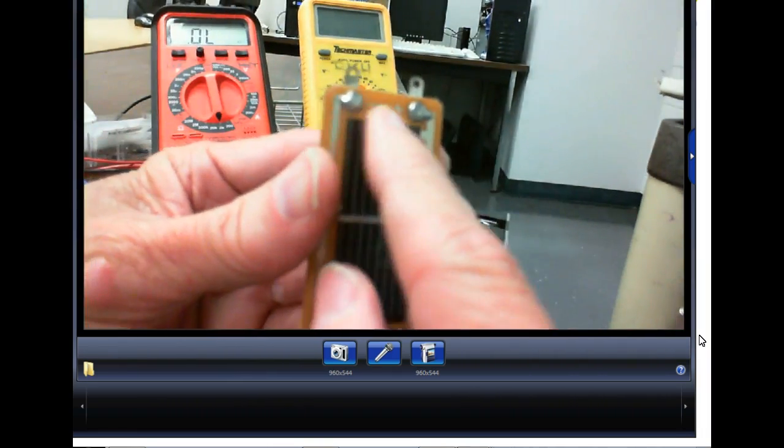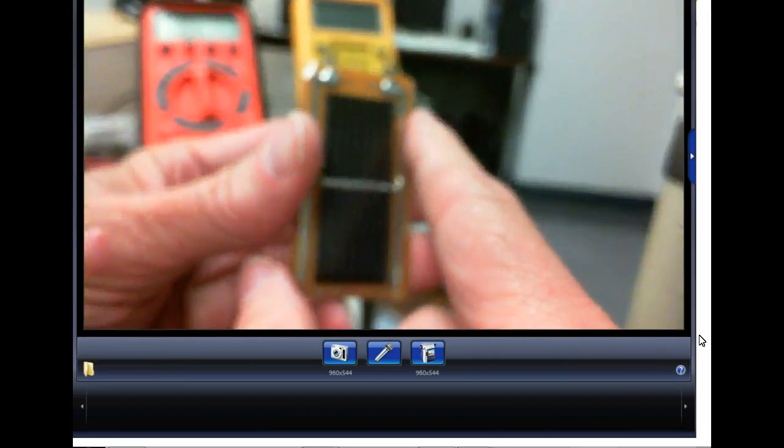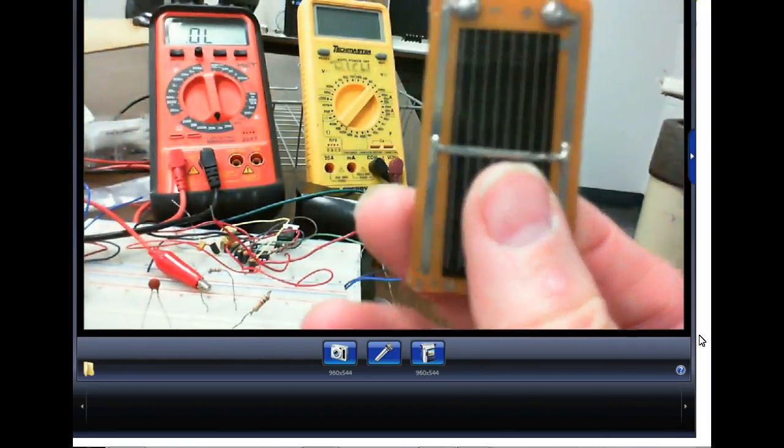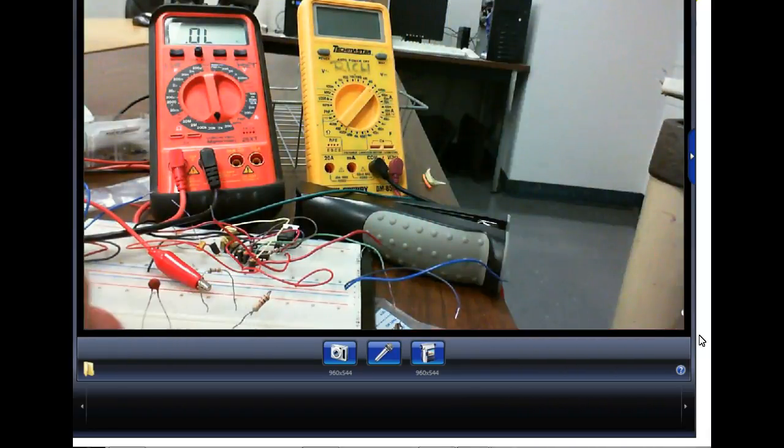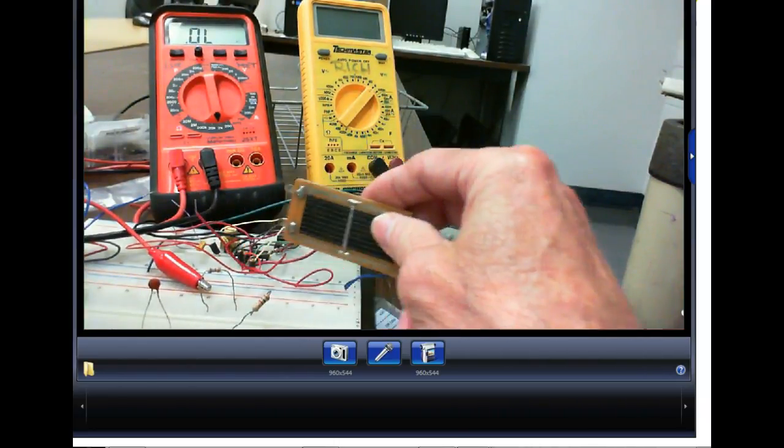She says that diode on the solar panel don't work anymore. But it's got a plus and a minus, and this guy's got two terminals up here, so we can hook in series, or we can hook in parallel. These guys do not vary their resistance. So my thermistor, what would I have to do on that thing? Well, I'm going to have to put it in series with a resistor, right? You understand, to take a resistance and convert it into a voltage. We don't have to do that with these solar cells or these photovoltaic cells.